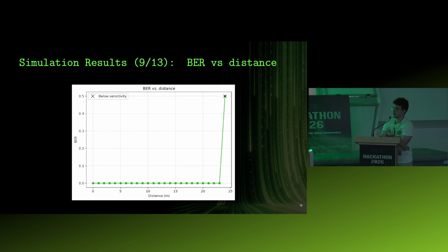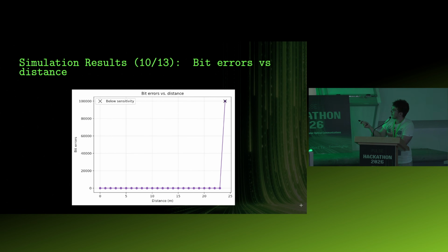What we did is first compute the bit error ratio with a maximum likelihood decoder, and then utilizing the values that we got earlier with the channel response, trying to compute the maximum link distance, utilizing another parameter like the BER, and this is basically the limit. For another check-in, we also did a recount of the number of photons transmitted, and we get basically the same result.